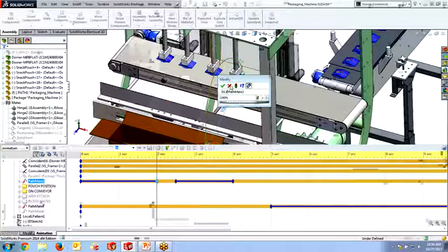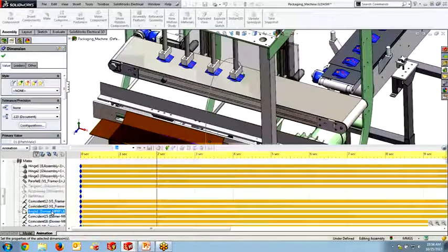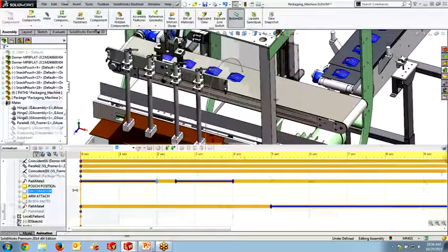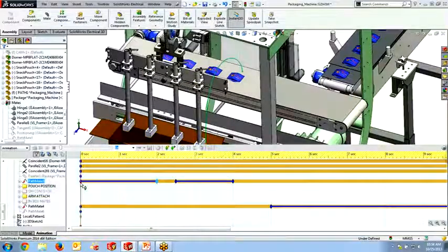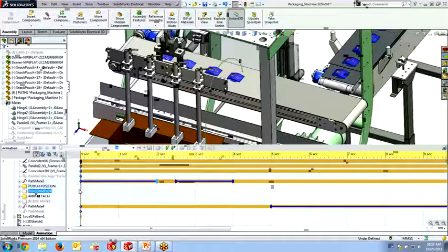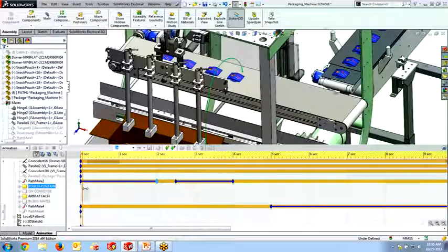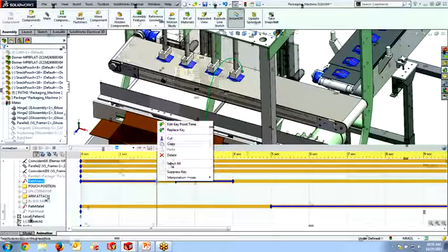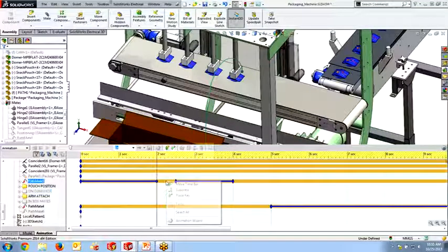So the way that I would create this inside of SolidWorks Animator is by first defining that: drag the time bar over here. I would define this by double-clicking on it, keying in 0% for the timestamp there. That would create a key, and then I would drag this time bar over here, right-click and say Add Key, which you would see if there was not a key there.